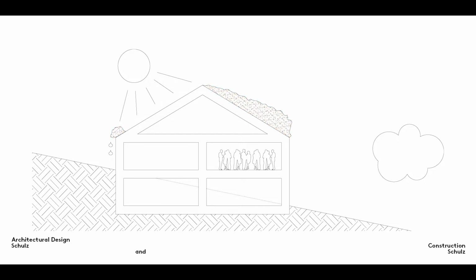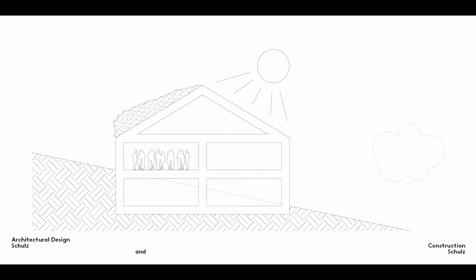Live loads can be deceptive. Sometimes they are there, sometimes not. The stress on a balcony, for example, changes when everyone at a party suddenly decides to go outside. The various scenarios to which supporting systems are subject are known as load conditions. A load-bearing structure must be designed and dimensioned to remain stable in all load conditions.